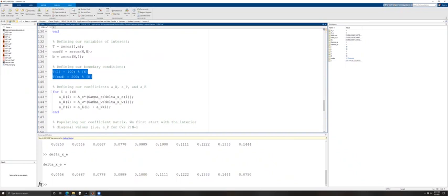Now, what's really nice about this is since we already had delta x and then delta x east and delta x west defined as a function of length, when we define our coefficients a east, a west, and a P, we can just call in delta x east, delta x west, and then what we solve for. We don't have to necessarily do that special 1/2 and populate that at the end because this is already pre-computed. So we have to make sure though that these are a function of our space, i.e. which control volume they're being evaluated at. So we do a simple summation.